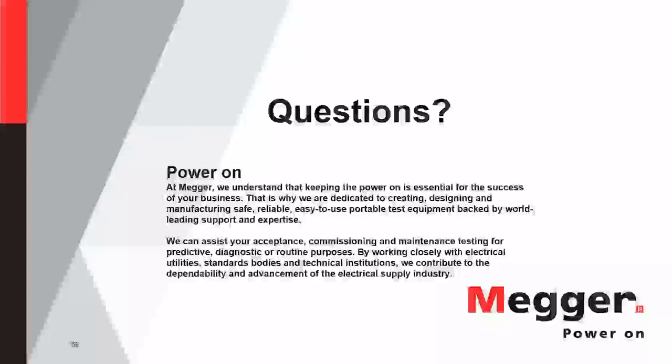Now, when you get to 365 kV and above, the mechanisms don't have enough energy to be able to drive all 3 phases and interrupt all 3 phases at the same time. So now you have a separate operating mechanism per phase. So we call that an IPO, or independent pole operated circuit breaker. So now you hook up a transducer to each mechanism or each phase, and you measure all 3 of those. So really it should be gang operated and IPO kits, but we just call it single phase and 3-phase kits.